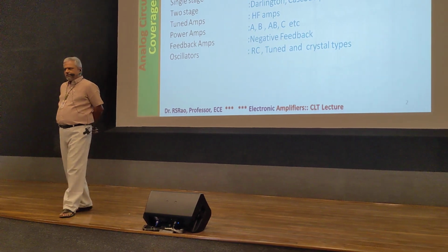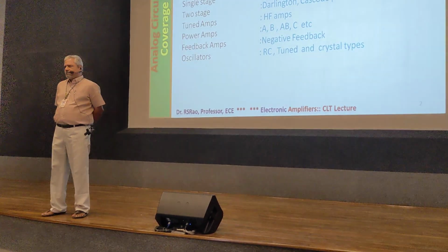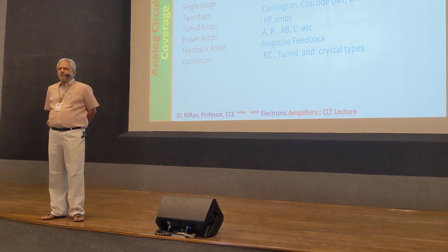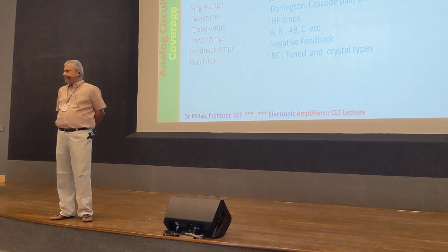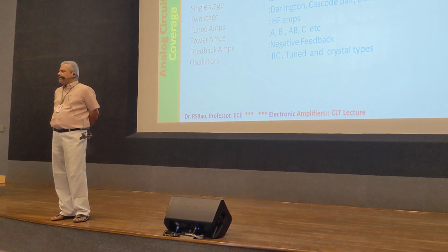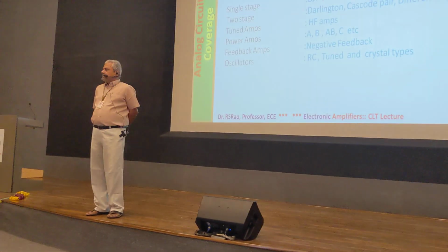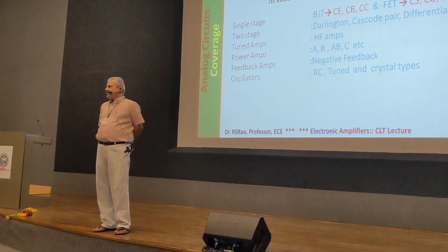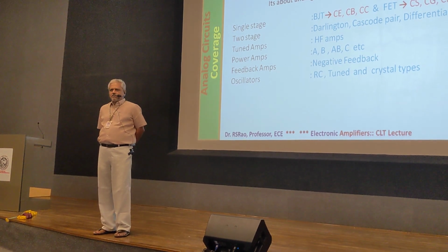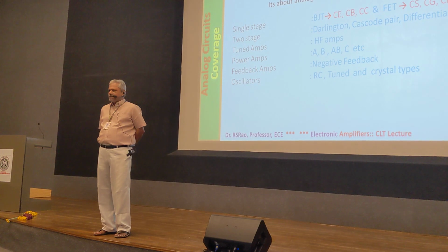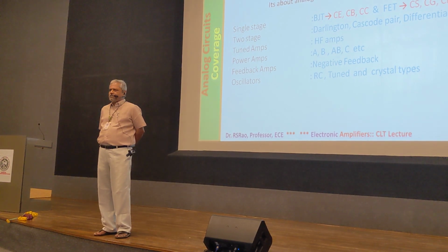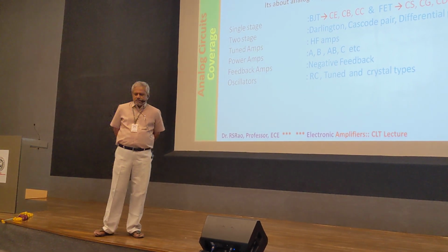As already told you, CS also has this high frequency limitation, a narrow bandwidth problem. If you go for the cascode configuration, then CS also gets rid of this issue. Now you can use it. Everything is fine, spotless, extremely good performance. Okay, so that is cascode.